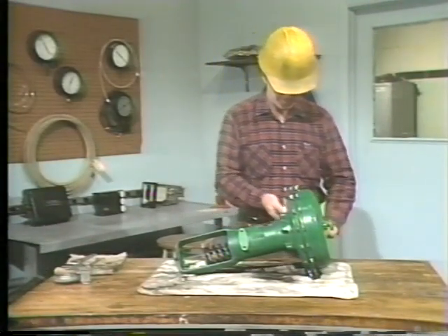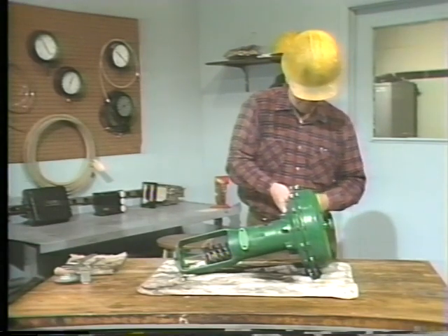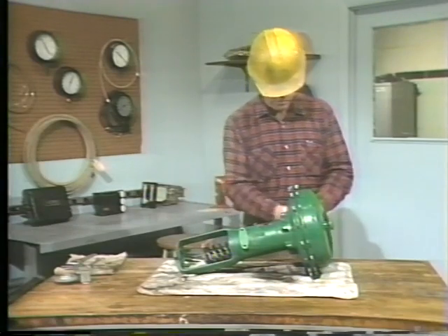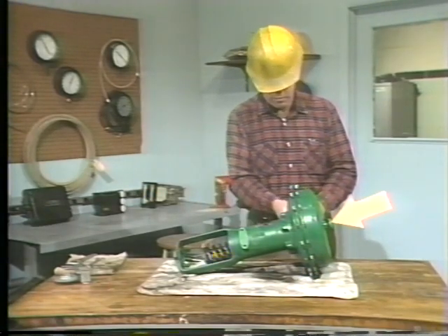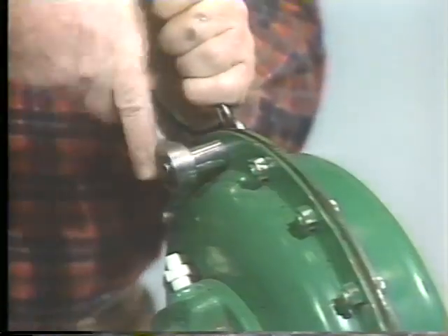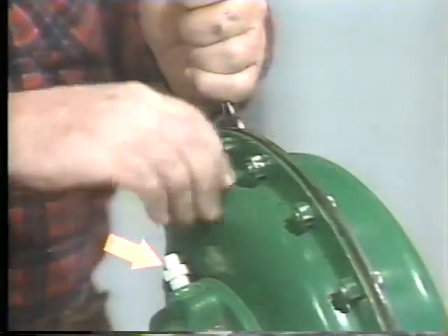The diaphragm casing is divided into two sections or chambers, an upper chamber and a lower chamber. This actuator has a vent in the upper diaphragm casing which allows air to move freely in and out of the upper chamber. This vent should be cleaned as a part of the maintenance and must be kept clear so the flow of air is not blocked and the actuator can operate properly. The lower diaphragm casing of this actuator has an air port. Air is directed through this port to provide the force that makes this pneumatic diaphragm actuator work.